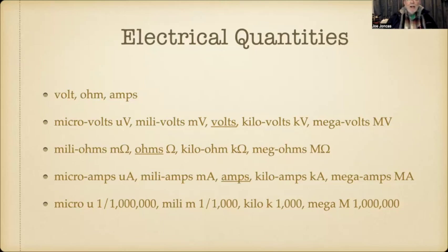So let's talk about ohms. We talk about 10 ohms, and we've been using 100 ohms for our project so far. We've added 3 in series and had 300 ohms, and we've had 3 in parallel and ended up with 33.33333 ohms.